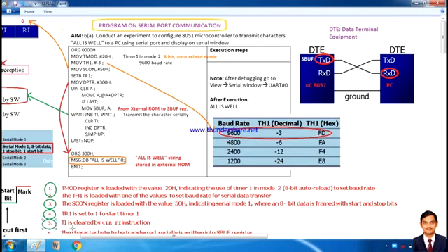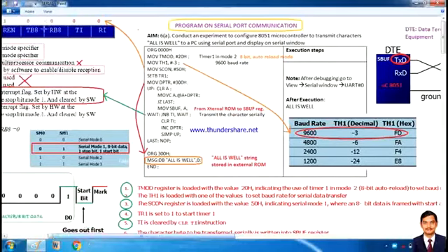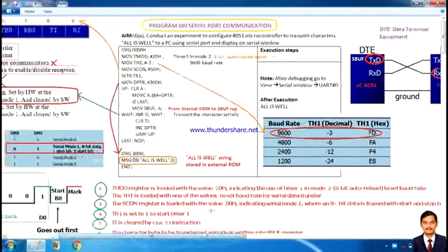Next, TI is cleared by the CLR TI instruction. This we have already done by passing 0 to it, so by moving that data we had already done it. By default it is 0, so we need not take care of this particular instruction.